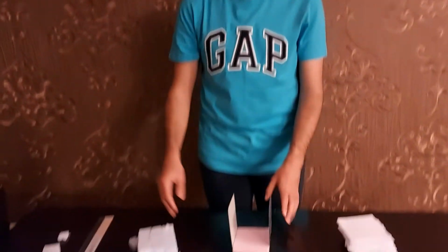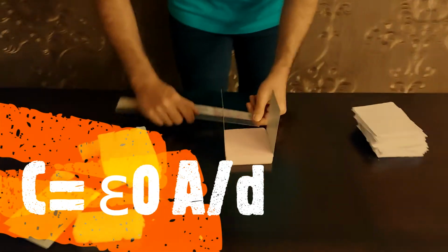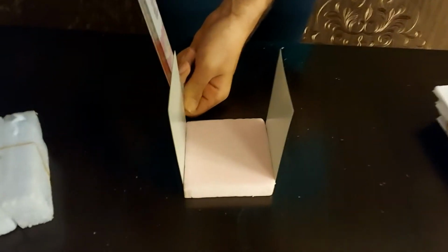Following that, I have measured the distance between two plates, width of each plate and length of them, to compute the area of plates and distance between them, because it would be useful for the calculation of capacitance using the associated formula. I have measured them like this and noted down the values. Following that, I have placed different dielectric materials in different proportions as stated in table 1. Table 1 is given.